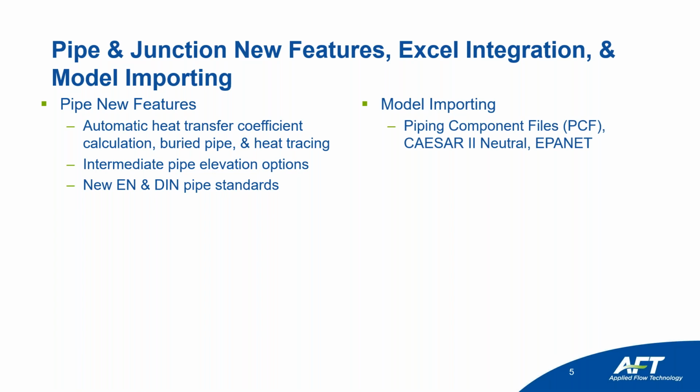And so things that we can import now, piping component files. So if you have an isometric drawing from one of your CAD programs, for example, then you can import that PCF file and it will build the model and the layout of your system for you.